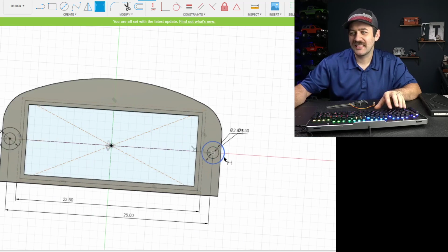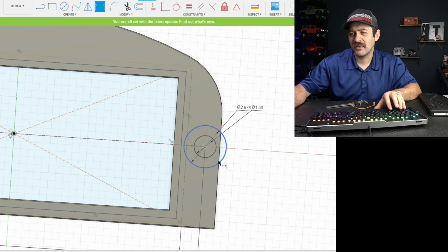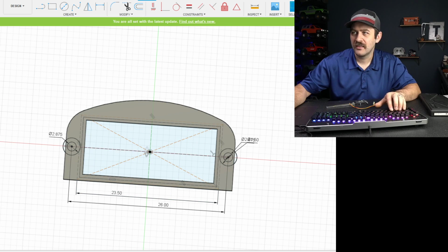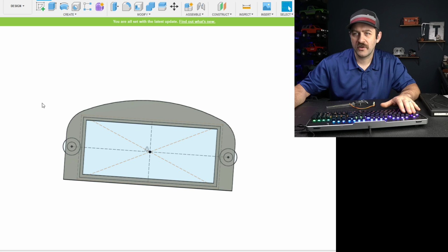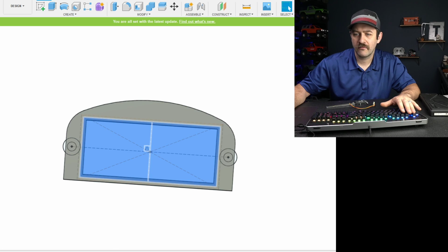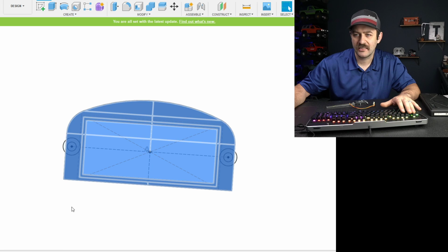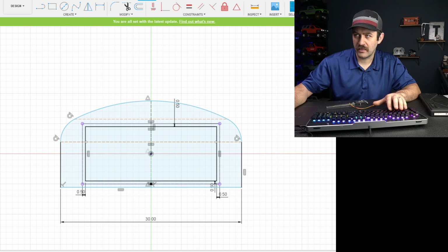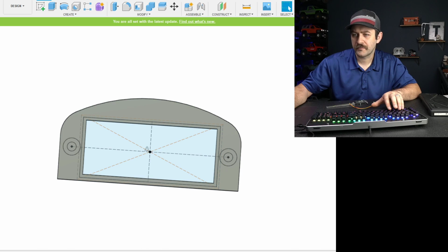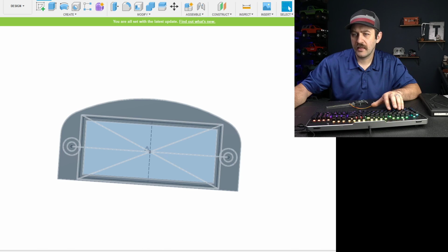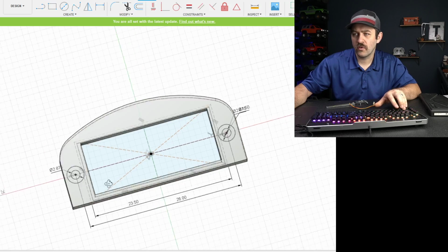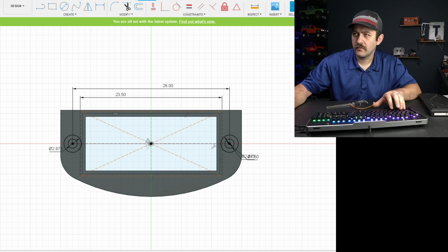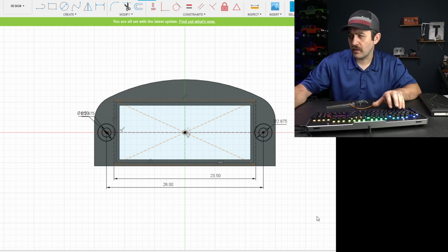So one thing is that you can see our boss's area now is kind of going over the actual area for the voltmeter. So instead of allowing that or trimming that, we'll go back to our second sketch technically. We're just going to increase this thing to 30 millimeters, then that gives us a little bit more to work with. So let's rotate around so that we're just looking at it in a way that we're familiar with.